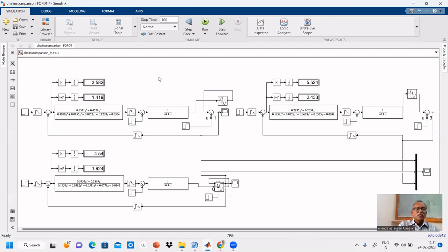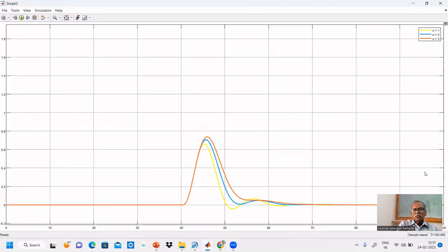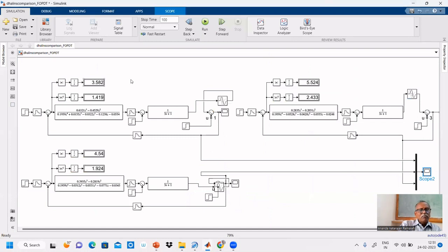The highest is for the open loop time constant equal to closed loop time constant. Let us see the response. Yellow is for mu equal to 1, you got better dynamics here. Better dynamics because it is the ideal case. The controller for which it is designed is e power minus 1.346. That's why you can notice that ISE and IAE are also lesser compared with the fourth order process.